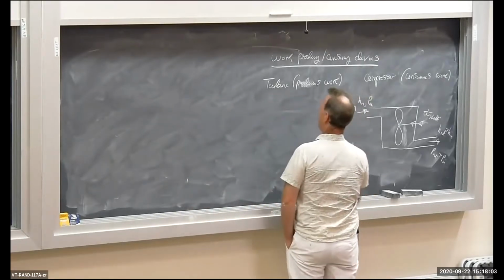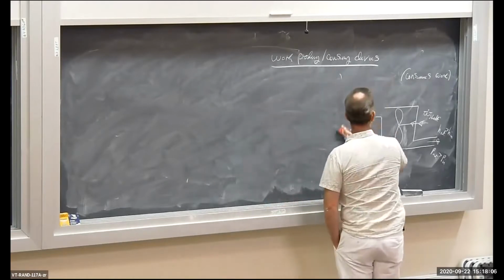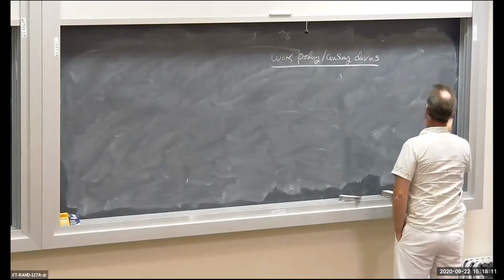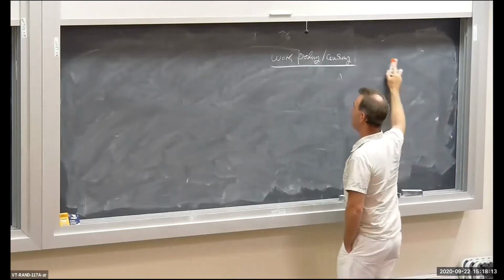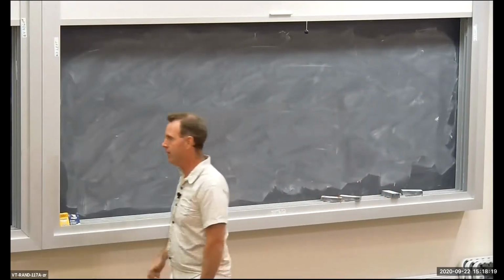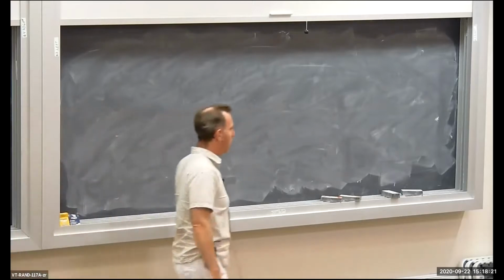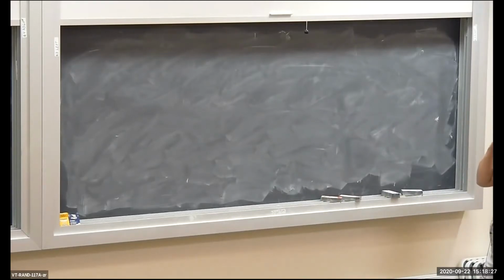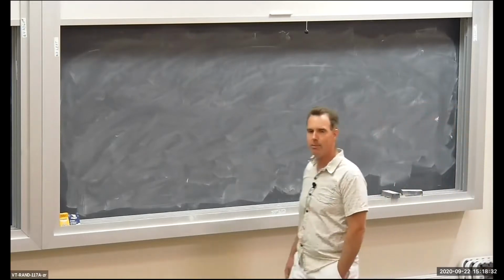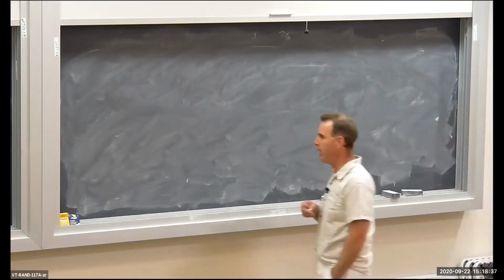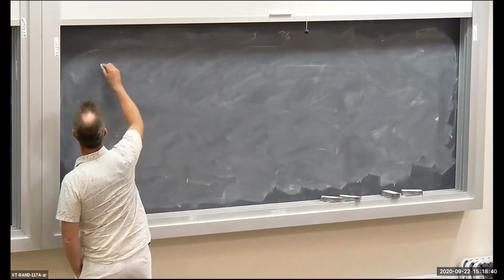Well, if we knew some kind of property at the outlet, a specific enthalpy or an internal energy, and we assumed ideal gas behavior, it is air after all, we can probably assume ideal gas behavior, but maybe we should check to make sure that the temperatures and pressures give us a Z value, a compressibility factor, close to 1. So if I know the specific enthalpy or internal energy at the outlet, I can back out from air tables what the temperature is, okay? So somehow I need to get the outlet enthalpy or internal energy.